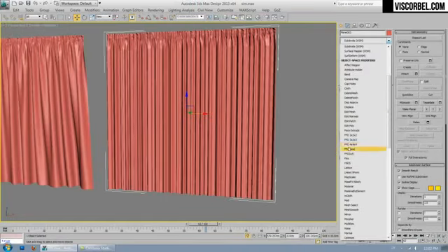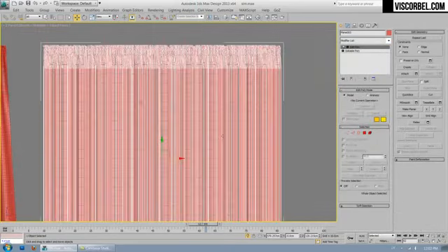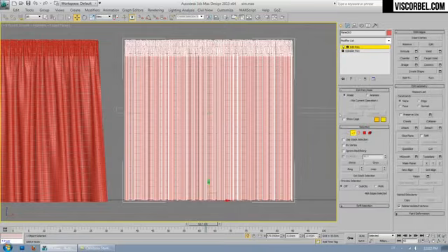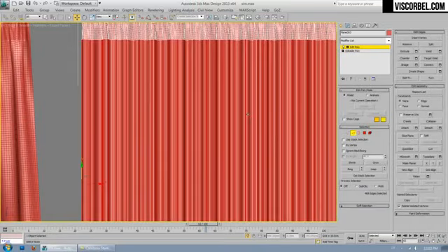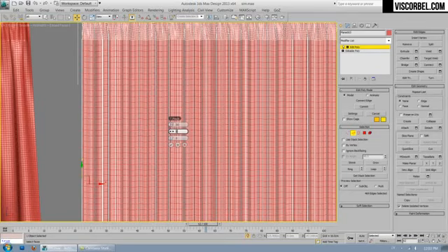And let's add the smooth modifier. So first let's add the poly. I want to add some more detail here. I can do that by connecting these edges. I don't want the grid as tight as on this upper level, but maybe like 50 or 70 subdivisions. Okay, let's say 70.